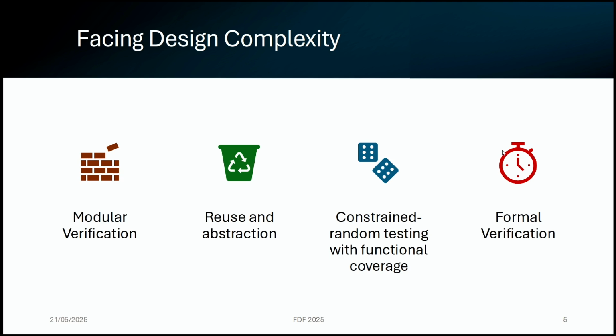Let's start by looking at design complexity. So one way I really like to tackle this problem is by modular verification. And by modular verification, I mean, I like to take my design and break it down as much as I can into smaller bits, and then verify those bits independently. Usually large designs have big hierarchies, deep and wide. And so what you do, you take this hierarchy and you say, okay, can I isolate some bits of this hierarchy? And if I can, probably write a verification environment around it.